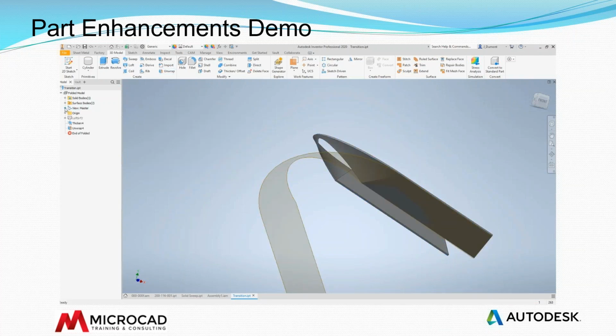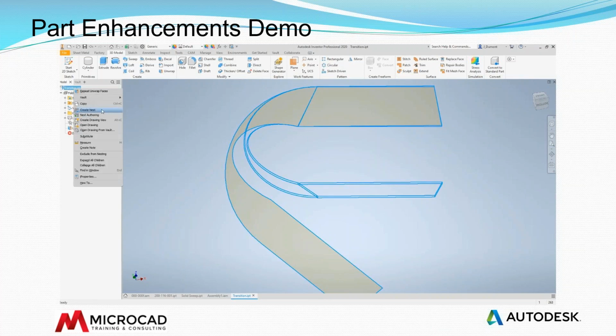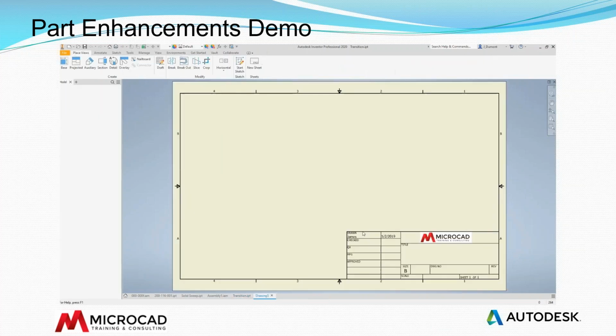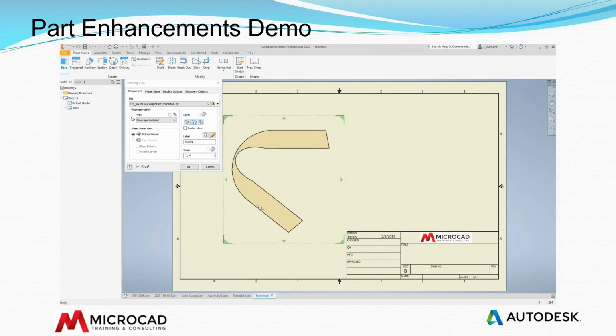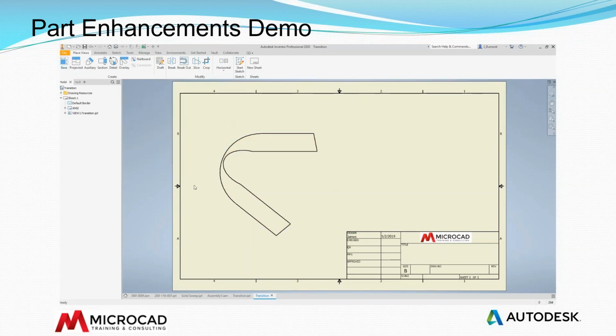Inventor will create another design view within the part file that's called Unwrap. And when I double click on this, activate it, I'm looking at one of the planar faces of this unwrapped feature, and this gives me the ability to create a drawing. As a normal process, I'm going to create a drawing view of the part file, but within that design view. I can select it, scale it, locate it, and now I can dimension it as I would normally.